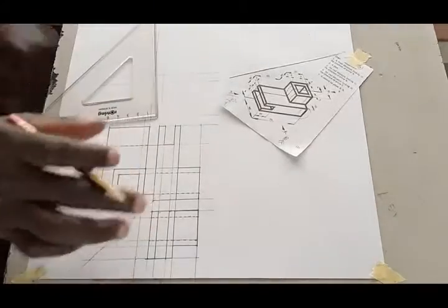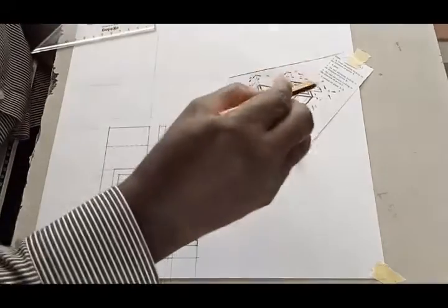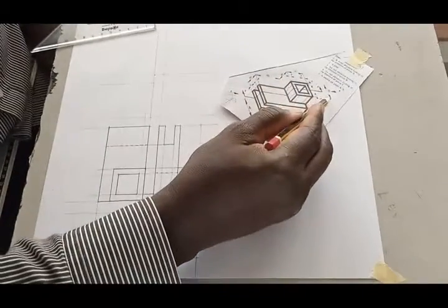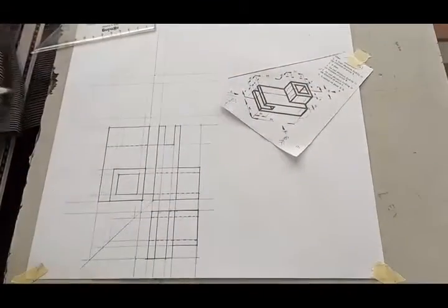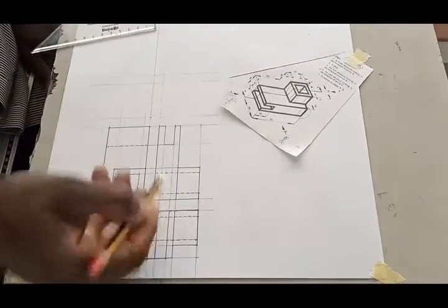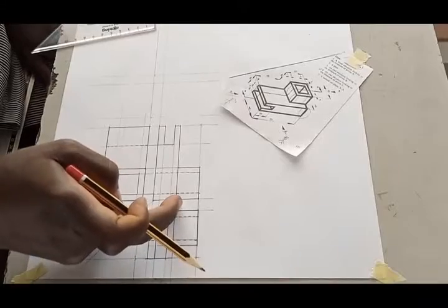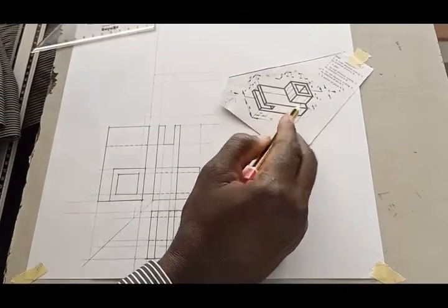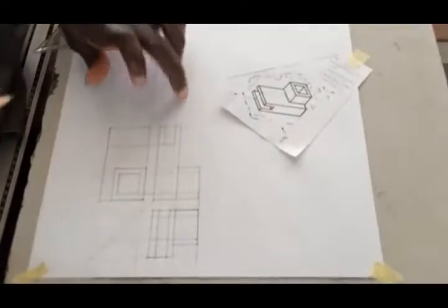So now we have been able to draw three drawings, remaining two. We have done elevation in the direction of arrow C. Now elevation in the direction of arrow B. That is the fourth question. So when we are viewing it from this side, you draw to the right because this is the left. I mean the right, you draw to the left. You are viewing from here, you assume you are here, front elevation. So this arrow B is by your right, you draw it to the left. So it will be placed here.